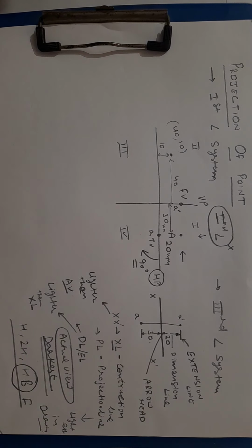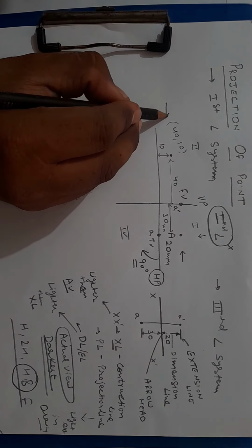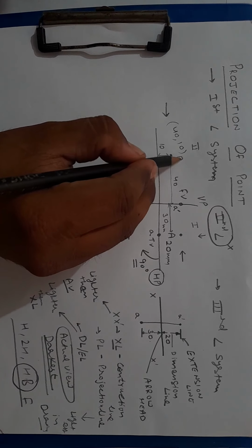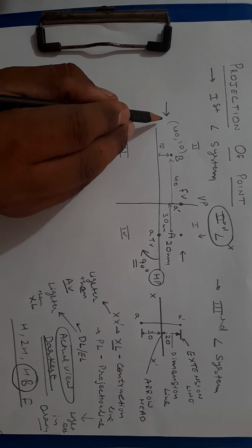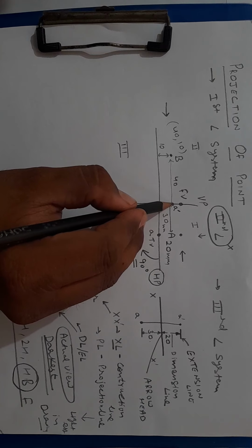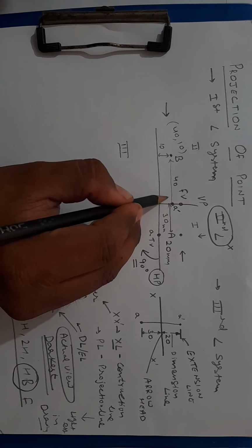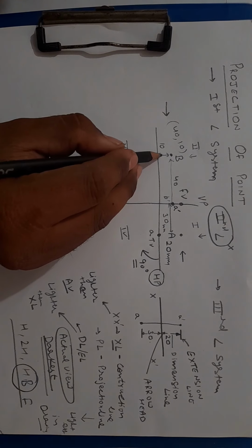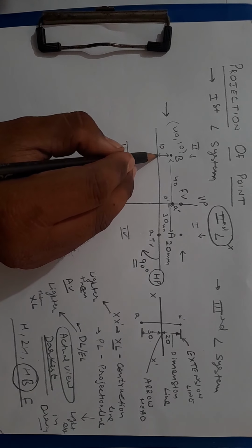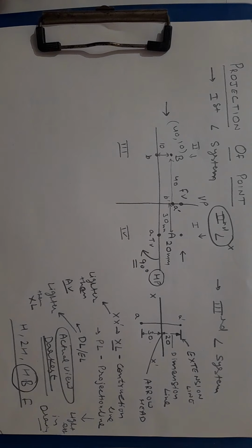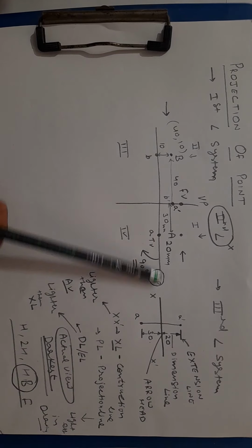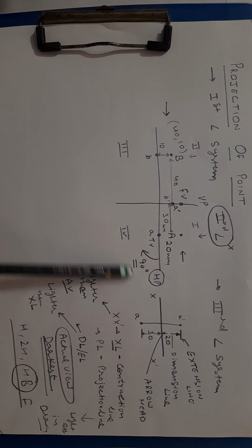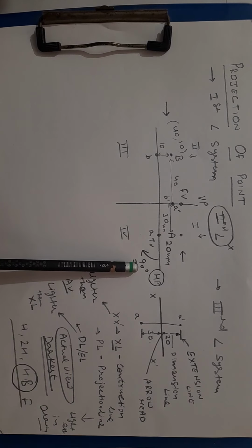We can also plot this. When we observe the point B, its image will be over here on the vertical plane as front view B dash, and from here the top view will be over here as B. We know we need to move this HP clockwise by 90 degrees.